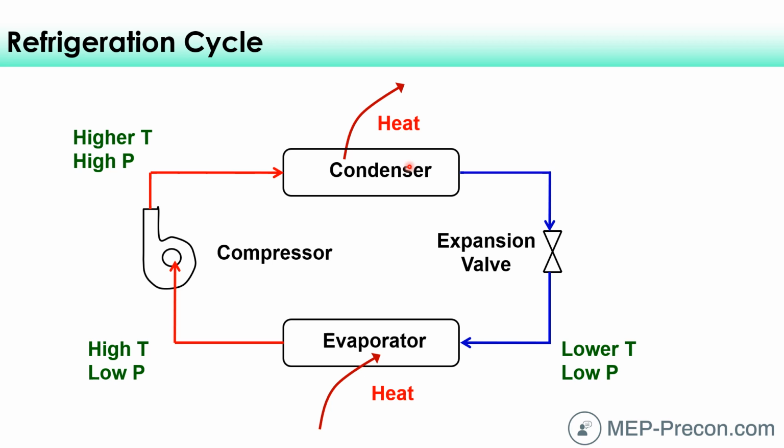They're not so small that they stay invisible within the air. They get so thick that they just can't stay in suspension anymore, and they form this cloud. And eventually up in the atmosphere, they collect on dust particles, and they get bigger and bigger, and that's how rain forms. That's how rain falls to the ground. Well, the same thing is happening in here with this condenser, is we're going to cool the refrigerant down to the point where it's going to rain in here. It's going to rain refrigerant such that at the end of this condenser, it's going to all be back into the form of a liquid again.